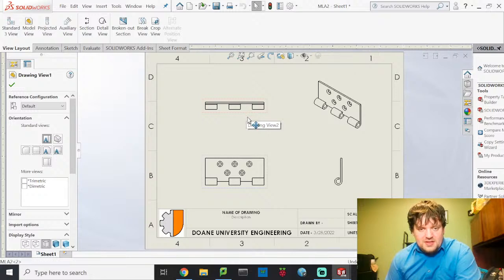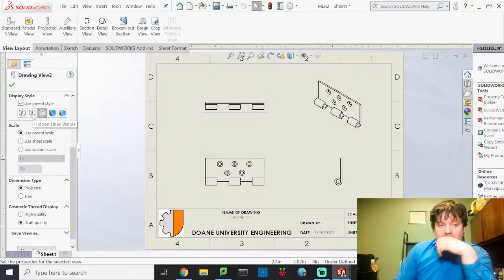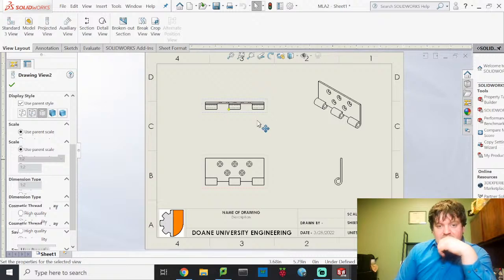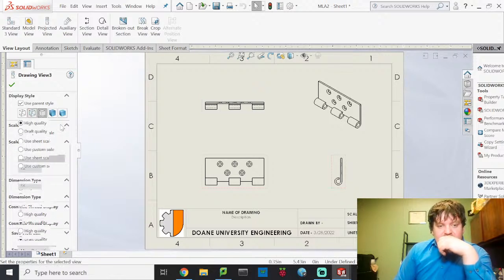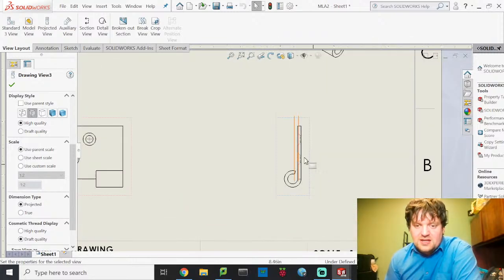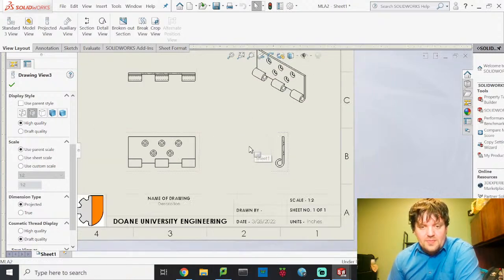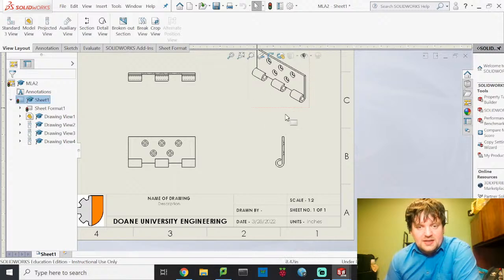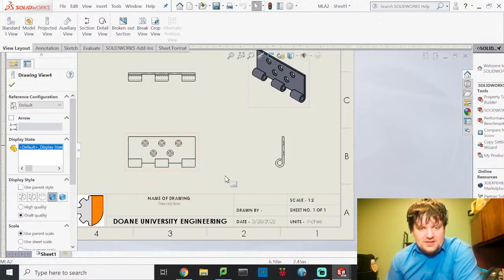What I am going to do on these is, instead of just a simple line view, which is what it has, I wanted to show hidden lines. So kind of give some axis representation there, and I'm going to do the same thing on this projected view. If you zoom in, it actually shows the countersink holes and how they're drilled. So there we go. And then second to last step, I'll pick this, shade this, and then I'm going to edit my